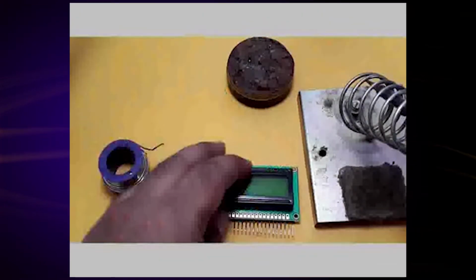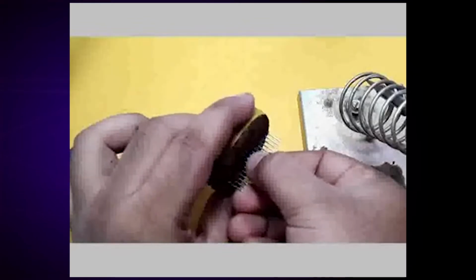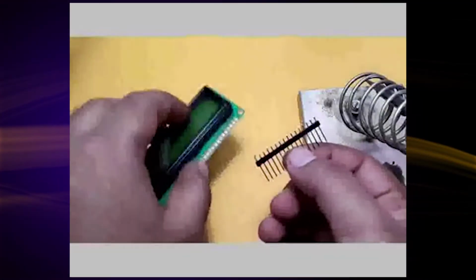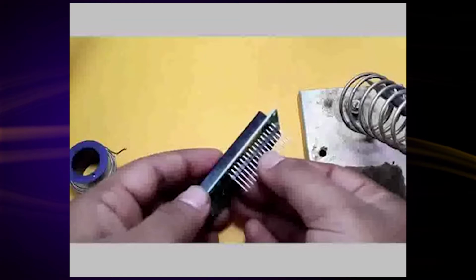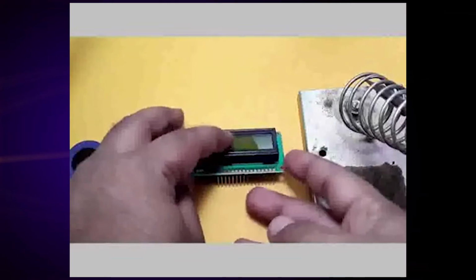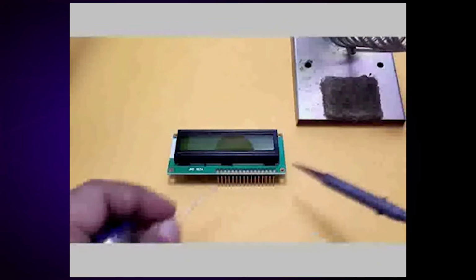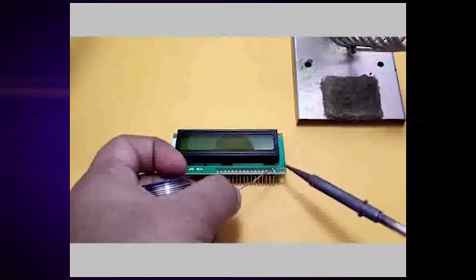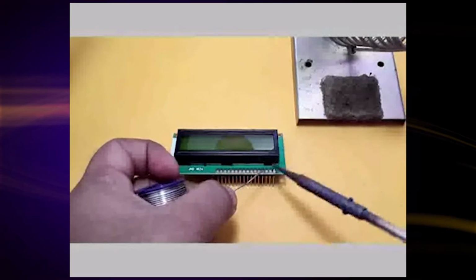First, put the external pin on the LCD as shown. Next, apply the solder paste to the tip of the external pins as shown in the video. Then, place the LCD with the external pin firmly on the flat surface as shown. Then, it will not shake while we do the soldering. Take the solder rod with little paste and touch the tip of the wire as shown. Hold it for few seconds so that the wire melts and apply to the external pin as shown.